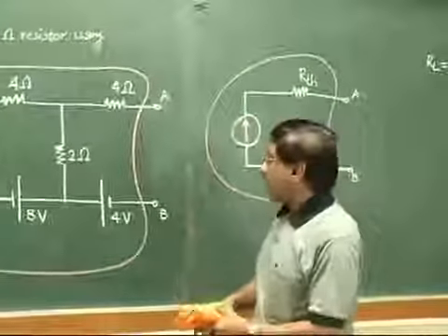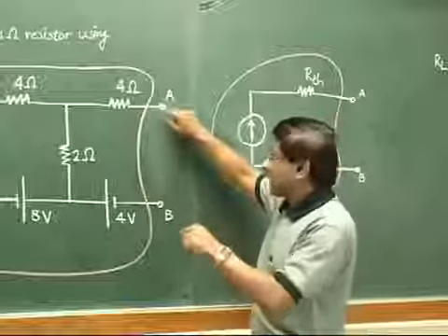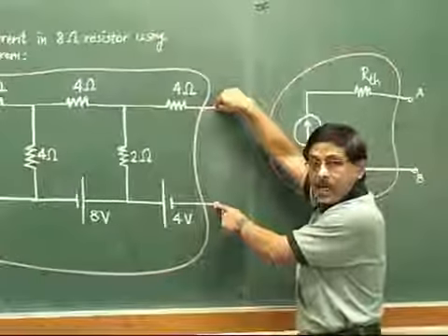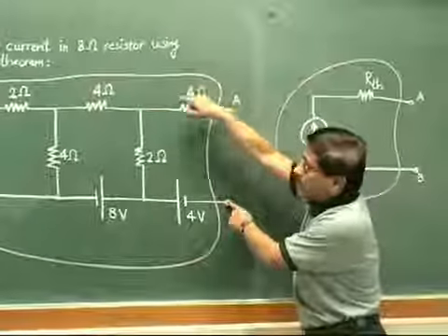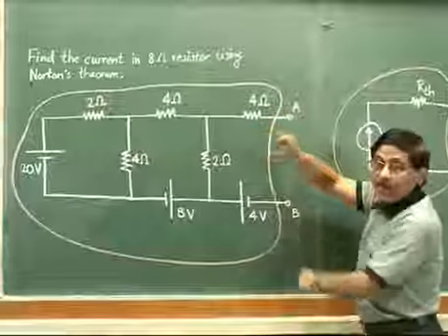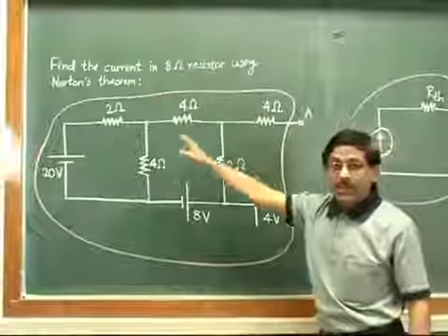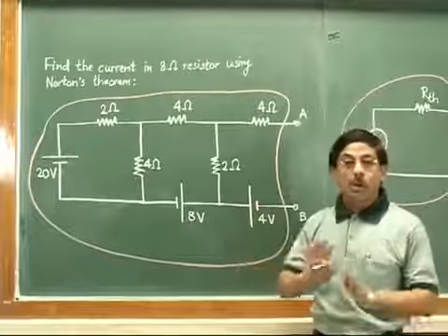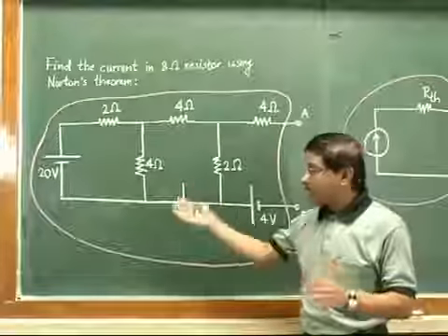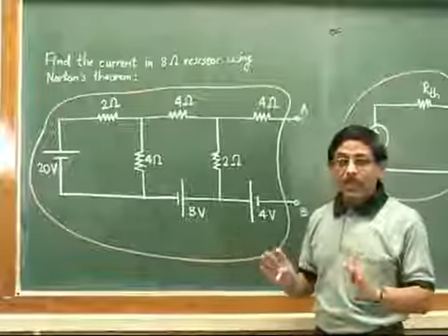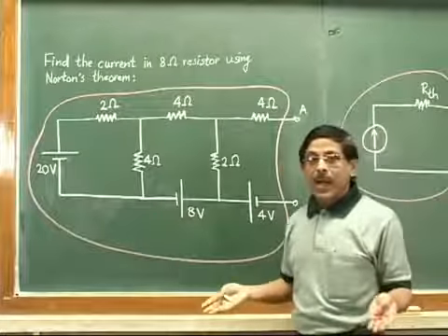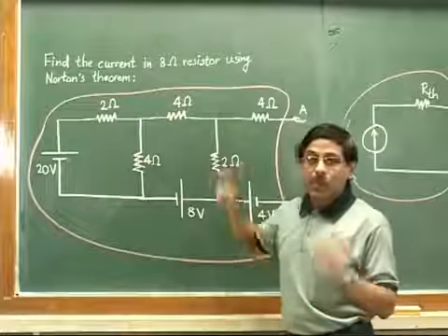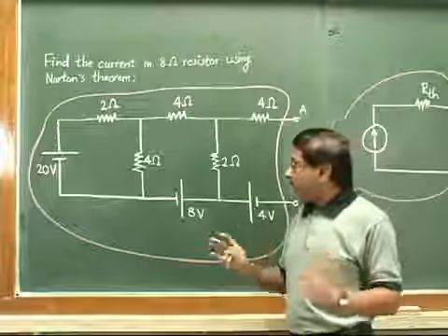So we have to find a single equivalent resistance across points A and B for this entire circuit. But that time we have to consider this circuit only as a passive circuit. That means the power sources are not acting, let there be voltage sources or current sources. We just replace them. There is a simple idea to make this entire circuit passive.